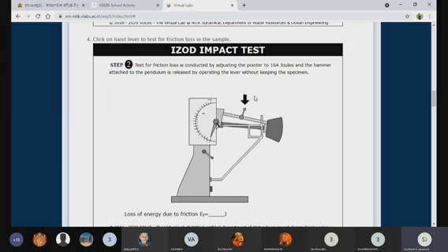Right? If it is Izod, we don't need to go to 130. Just the 90 degree of the pendulum is enough. So here, this is not exactly 90 degrees. You must ensure this because of the Izod test. You make sure the pendulum is perpendicular to the column, which means we are setting the 90 degrees without putting the sample, because we need to calibrate. We need to set the machine to zero condition. That will not show any residual stresses, it will show zero only.